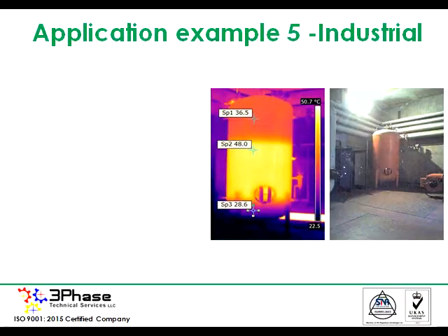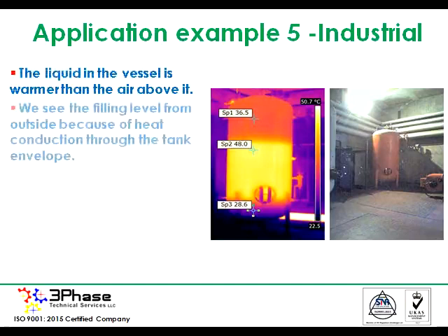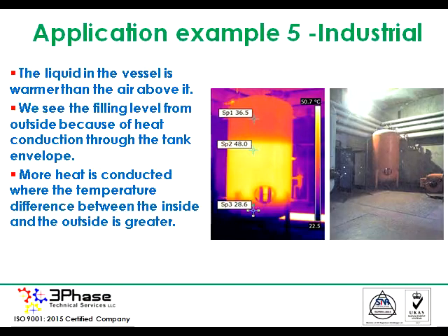Application example 5, industrial. The liquid in the vessel is warmer than the air above it. We see the filling level from outside because of heat conduction through the tank envelope. More heat is conducted when the temperature difference between the inside and the outside is greater.